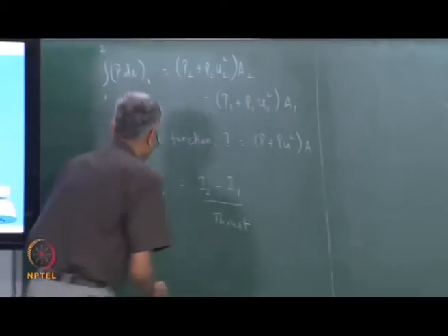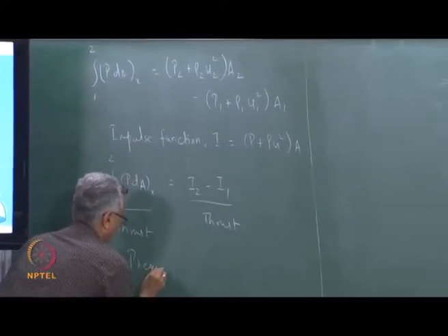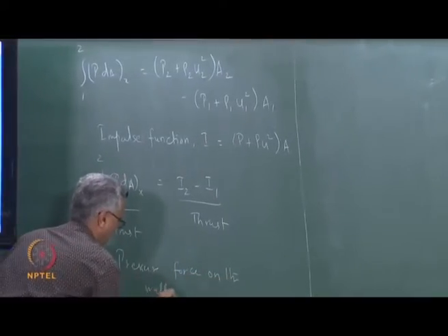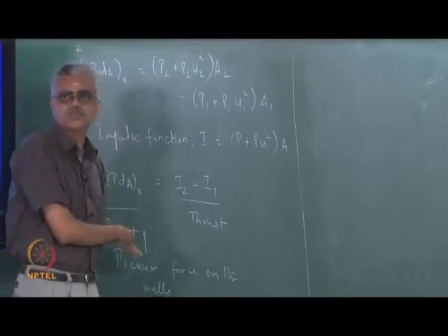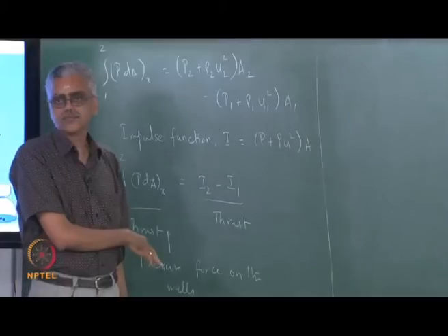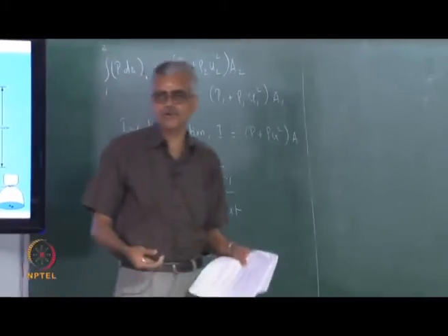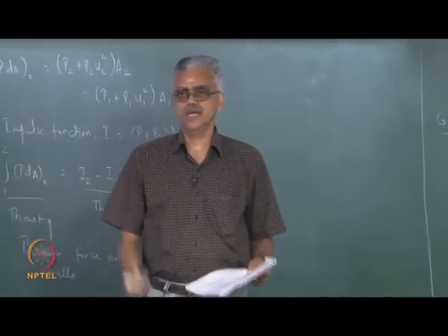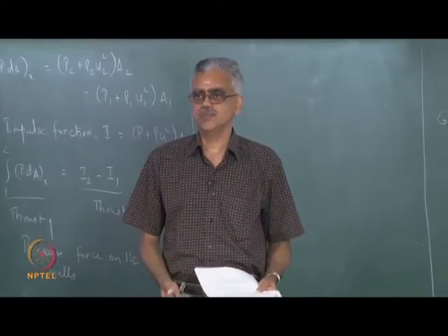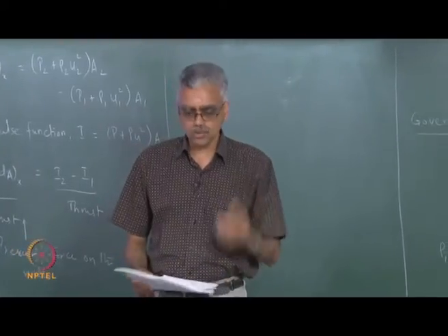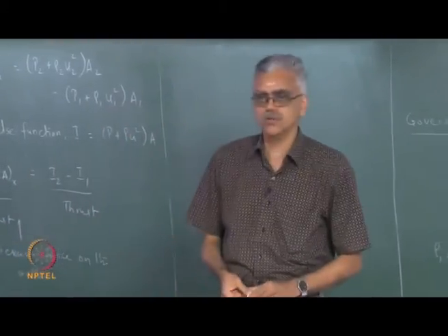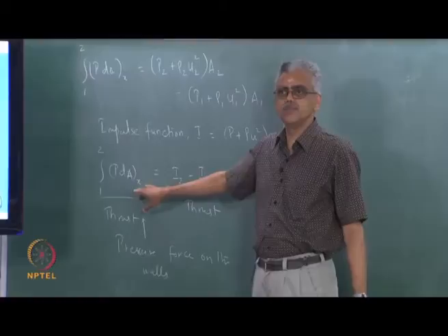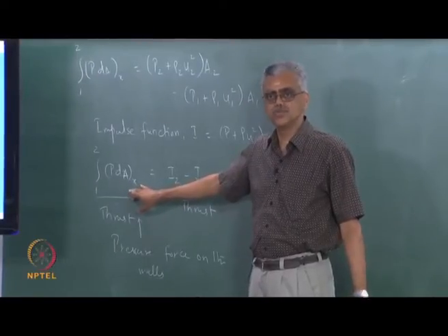This is pressure force exerted on the walls, which is felt. So, if you mount the engine on an airframe, this pressure force is what the engine would transfer to the airframe, which will then be realized as thrust by the engine. Okay. Let us take a closer look, because this concept is very important, although this quantity is very difficult to calculate in a practical sense. It is very important to have an understanding of what this force is and where it comes from.